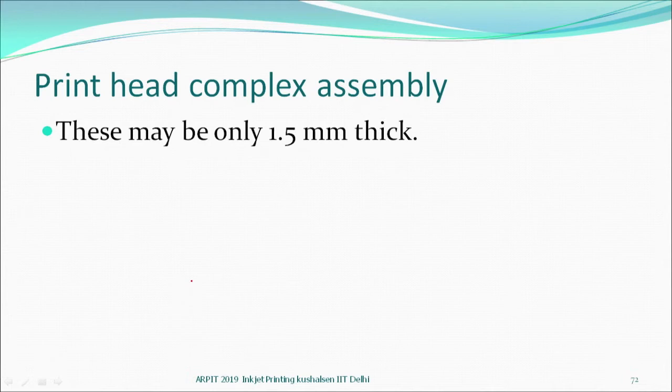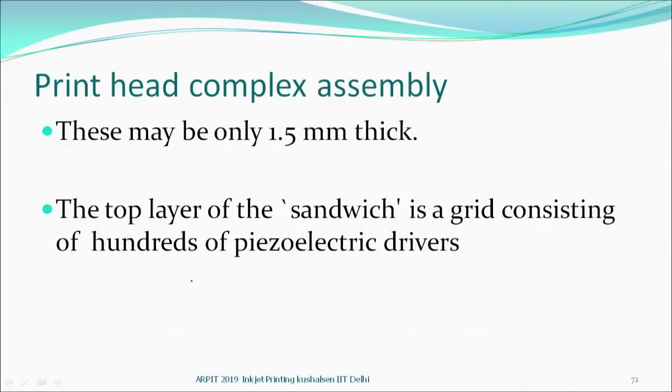And interestingly, these may be very thin, maybe 1.5 mm thick. Within this everything has to be done. There is a top sandwich layer which consists of hundreds of piezoelectric drivers which will be switching on, switching off, making sure a drop comes where the drop is required. It is already understood that there are, let us say, so many print heads and so many carriages, and which one is carrying which color. All that is a software controlled electronic system, which will ensure that the right drop comes at the right place.